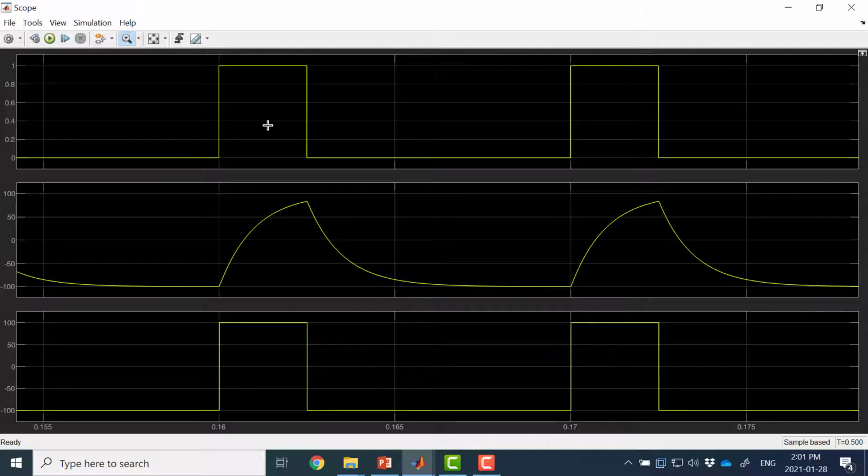Then 2D minus 1 gives me a negative value, negative half, times VDC over 2 should be negative 1/4 of VDC, which if you calculate the average in this square waveform, you can see that it is negative 1/4 of VDC, which comes to negative 25 volts.